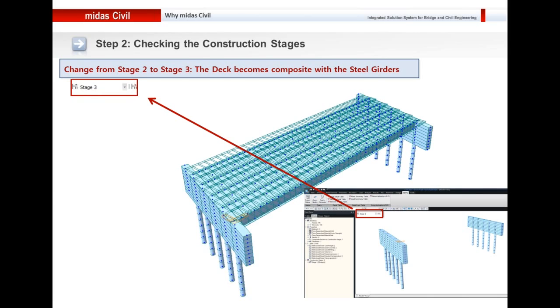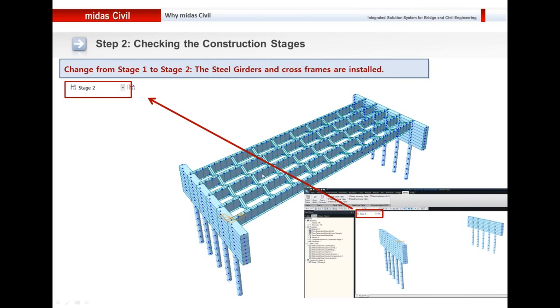The stages are important to model in any bridge structure because the stress history would be captured when you model the construction stages. So think about this particular stage when the entire wet concrete load is being taken by the steel girders. So what happens is, when you calculate the deformation or whatever stresses that you obtain for this stage, they would be inside the structure throughout the bridge life. And if you do not perform construction stage analysis, you cannot obtain the stress history as such.